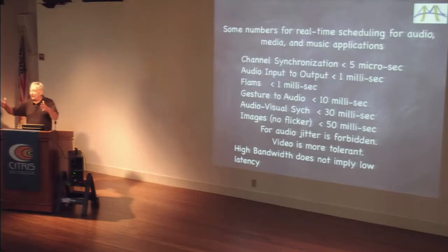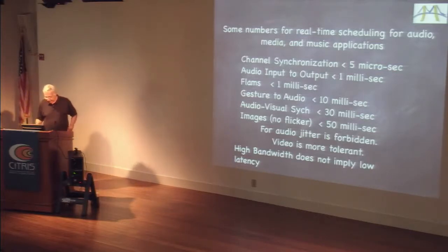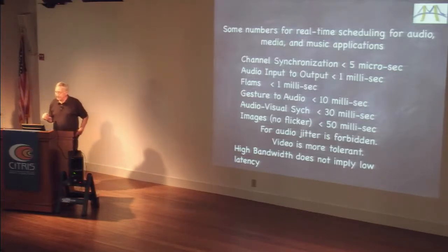Think of it this way. If your computation involves computing over a large array at one time, then you could see that the latency is going to be limited by the size of that array. So we have to have small algorithms that operate on small bits of data, and also we want to keep the I/O buffers on our instruments as small as possible. And sometimes that's a real challenge. So latency is a big challenge.